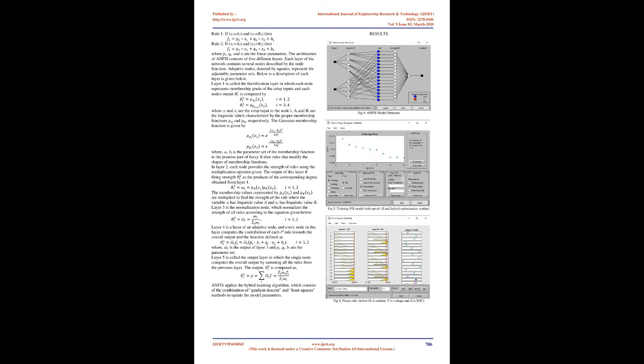Following are the steps to design a fuzzy rule-based model. First step, the input and output variables of fuzzy are determined. Second, the fuzzy sets are determined for each variable. In the third step, the membership functions of all fuzzy inputs and outputs are created. There are many different kinds of membership functions such as triangular, Gaussian, trapezoidal, etc. Since the type of membership functions impacts the design of the fuzzy logic controller, they should be chosen carefully. Fourth, the fuzzy if-then rules are generated to relate input and output variables. Fifth, the inference process is set.